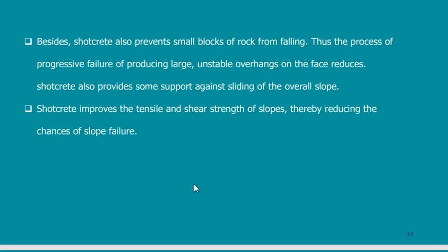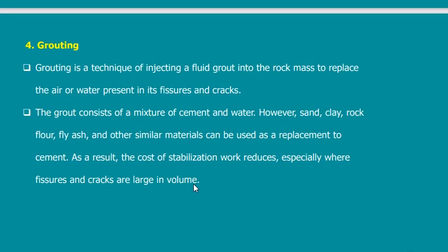This is all okay. Another method is grouting. I really do not like grouting in any geotechnical case because I don't guarantee grouting. What is grouting? Grouting is pumping concrete inside the soil. When you pump concrete inside the soil, it adds to the cohesion of the soil and the friction of the soil, because as if you are replacing the voids of the soil with mortar. So it is something very good.